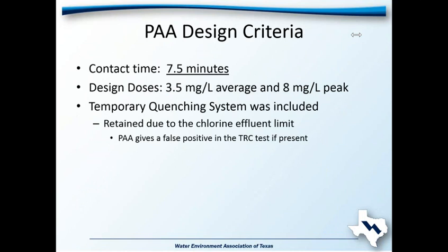Since we were one of the first systems, in fact, we were the first system in the state of Texas to use this, we were a little bit concerned about potential effluent toxicity. So we put in a sodium bisulfite quenching system into the design. After startup, we were going to test to see if we could operate without that and still not have any effluent toxicity issues. However,